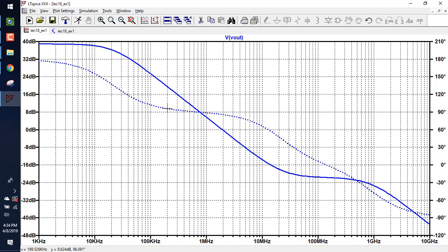Did anybody that took 220 from me remember that? When you do the frequency response, you look at the pole location, you go 1 decade earlier, means divide by 10, that's where the phase rolls off. 1 decade later, that's where the phase stops rolling off. Is that clear? That's how you do a Bode plot.